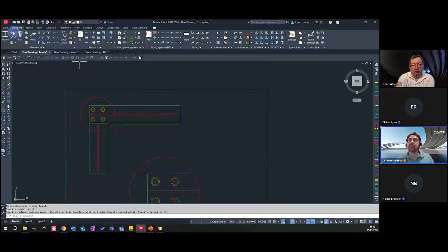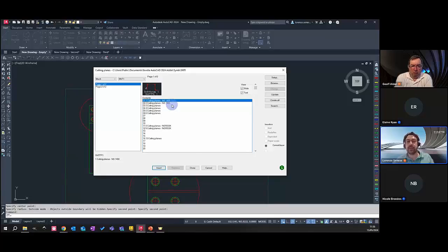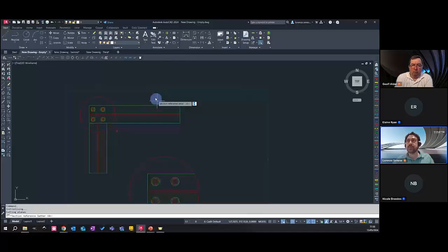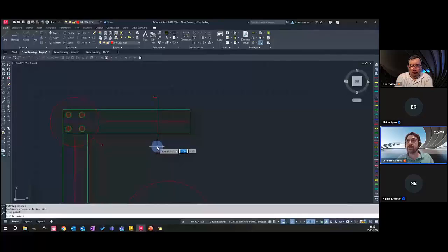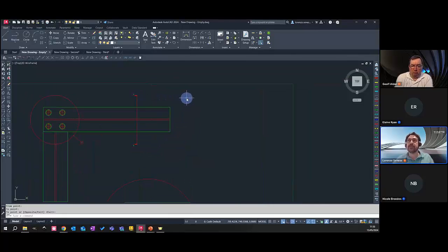Another thing that I want to do is the section. There is a feature, a Sovelia feature, to create section lines. So I can create section lines without worrying about the line type, placing the arrow, all the text. It is all pre-created. So I can just go to insert my section line, the reference letter A, enter, and then I'm creating the section in here. Okay, so you can see line type, arrow, leader, and letters all pre-created. Just with one click, I'm placing my section line.